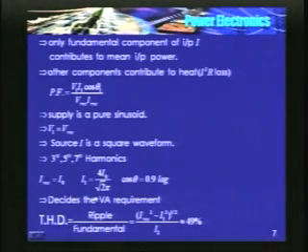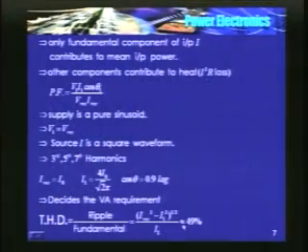It is given by, we have defined already, the ripple divided by the fundamental component: the square root of IRMS squared minus I1 squared, divided by the fundamental component. It is as high as 49%. Let us see sometime later in the course how exactly to reduce this total harmonic distortion. The 49% is the ripple content. It gives rise to only additional I square R heating in the load. It also affects the source side. We will see the effects sometime later.